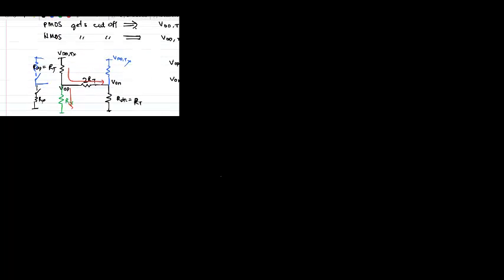So just do a sanity check: when we did not have any down resistance connected to ground in this figure, that means R down tends to infinity. Okay, so if R down tends to infinity, this term goes to 0, and then R up will be equal to RT. So you will have, there's something wrong there, wait.